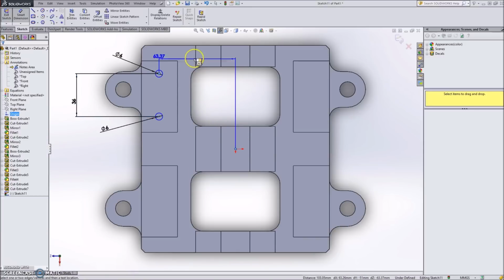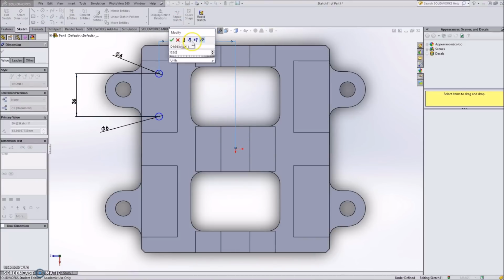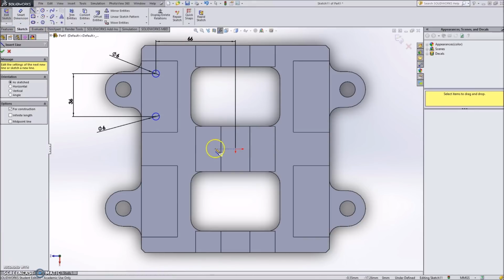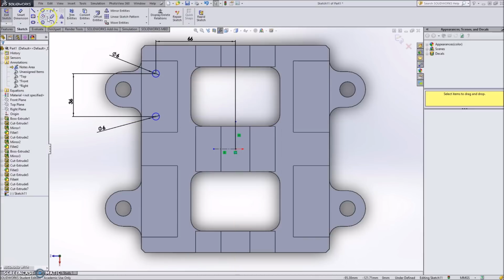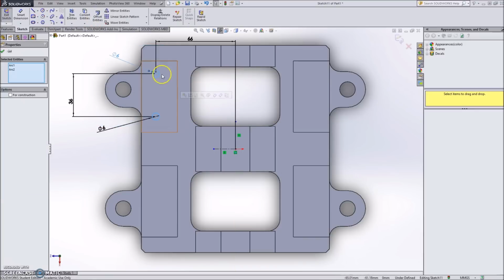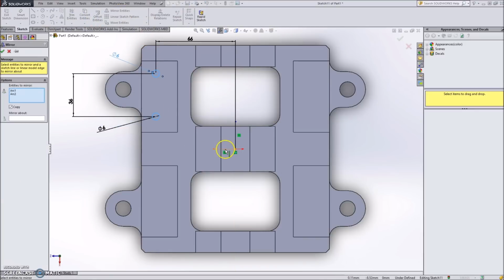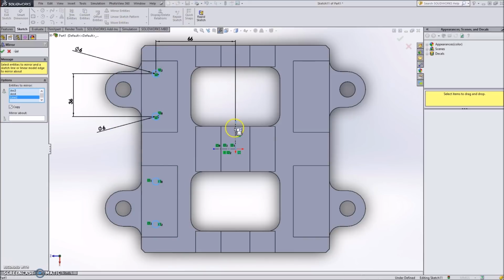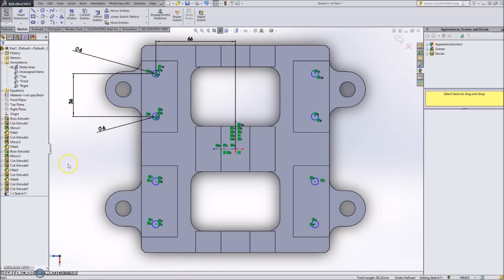and 132 divided by 2 millimeters from the center. So once again, take our center lines here, and we can select these two entities and mirror them across here. We can then take and select all 4 of these and mirror them across here. Alright, very good. Now all we have to do is create the holes in the centers of each of these